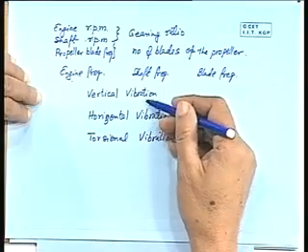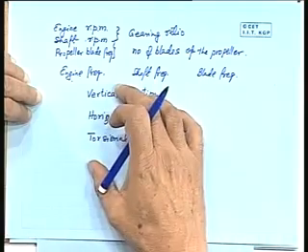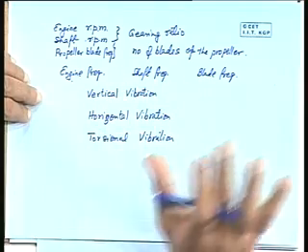Usually horizontal and torsional always come in combination, but for certain types of vessels the vertical and torsional will also be combined, especially with a torsionally weak structure. For example, container ships these days, open hatch container ships, are torsionally weak structures, and therefore horizontal torsional and vertical torsional will be there. So, instead of going into those details, we say that vertical, horizontal and torsional vibrations are the vibrations which have to be taken into account.